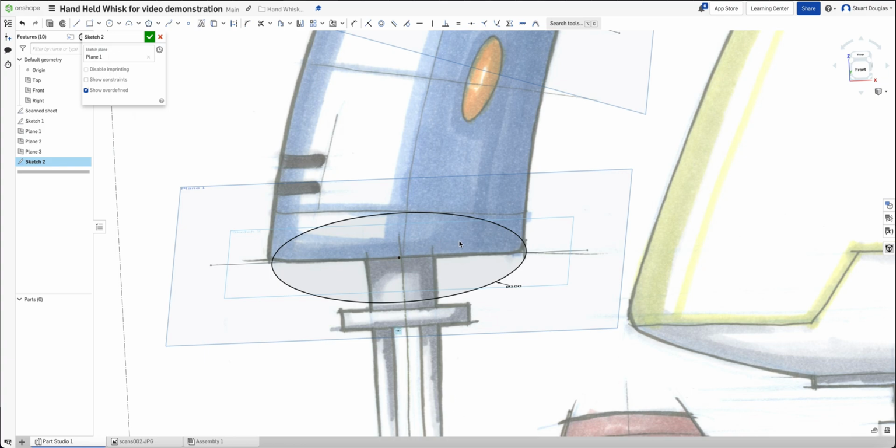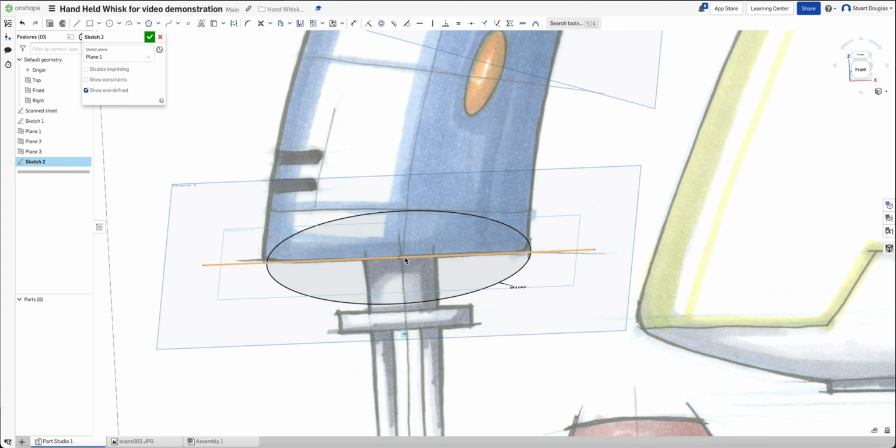So let's move it a little bit. Now, if you find that you can't move it, possibly because it's snapped, then as you see, I'm holding down the left mouse button here and I can't move it from the middle. I can't move it from the side. This is because it's got a constraint fixed to the circle for the center point. So we need to try and remove that constraint. If you just notice, I've just hovered over the middle. There's a little icon there. I'm going to click that and press delete. And now I can move my circle.